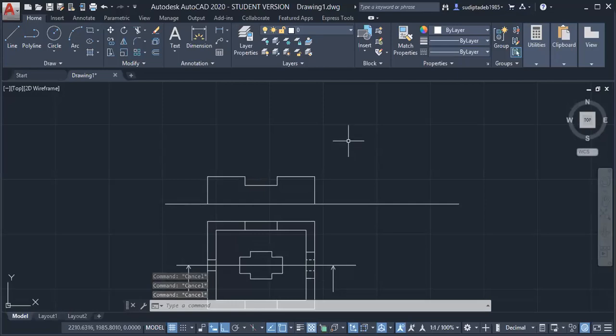So let me draw the other portions here also. Total height in the drawing, in the middle part, this part, total height is given how much? 20. In that corner, 20. And the thickness, that is given from all sides, is 8. So I am drawing one line from above.